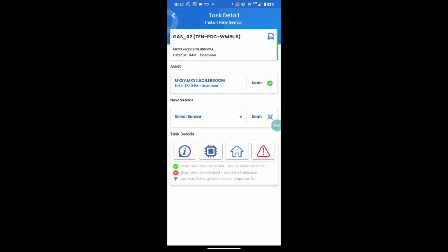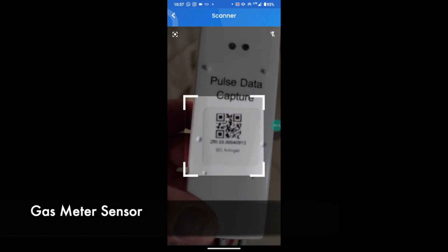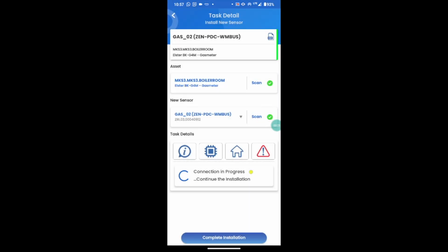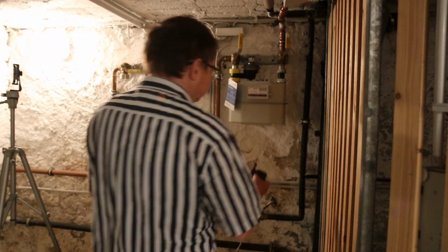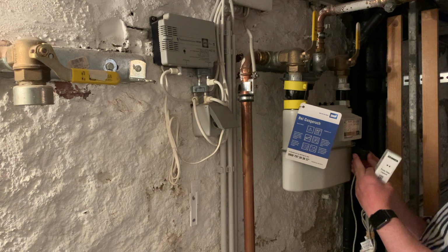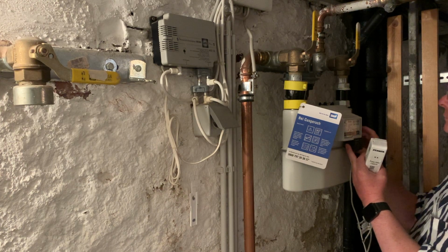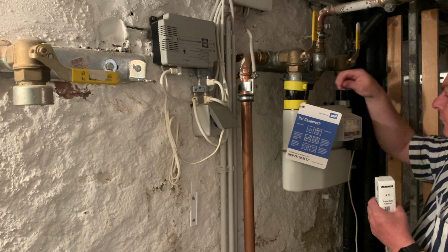The last sensor we are installing today is the gas sensor, with the objective to measure the gas consumption in the boiler room. Together with the two other values we collect, adding the digital twin information where we have number of units and building surface, we get a good insight into the boiler performance. Again, the installation is plug and play and intuitive. The sensor comes pre-configured from the supplier and allows installation without any specific knowledge of gas meters or taking any specific safety measures around the installation.